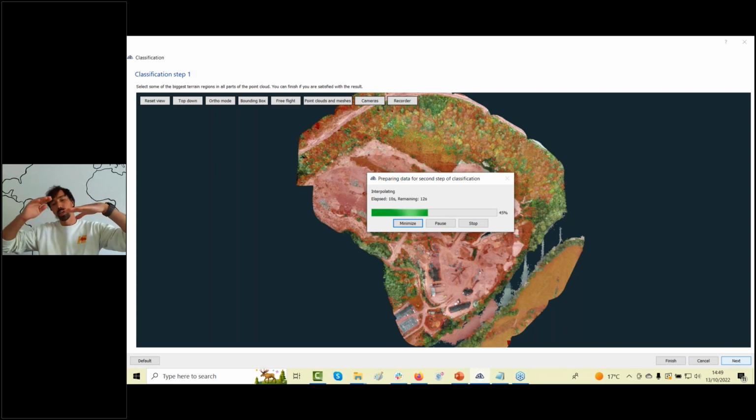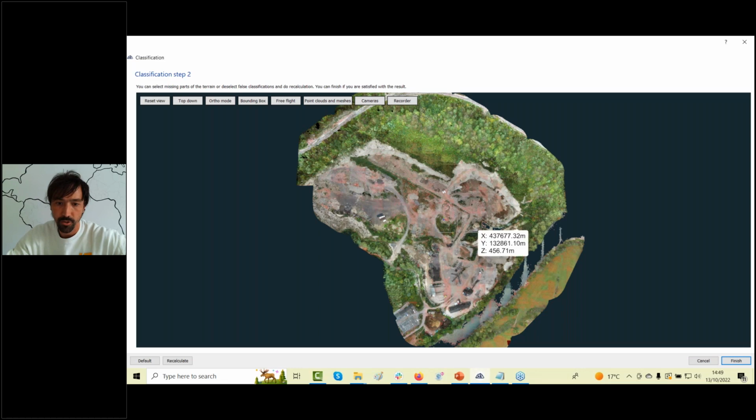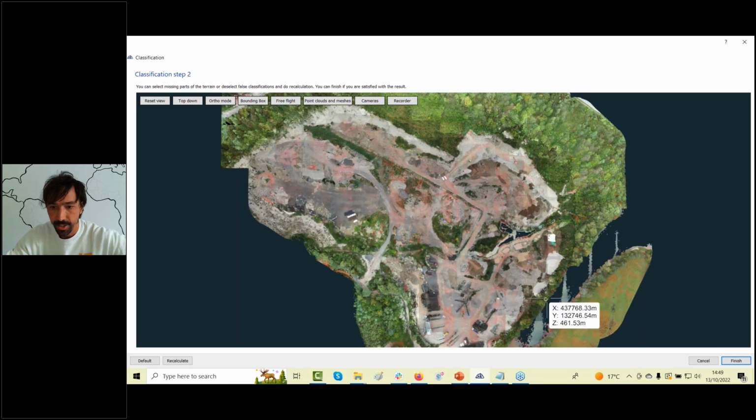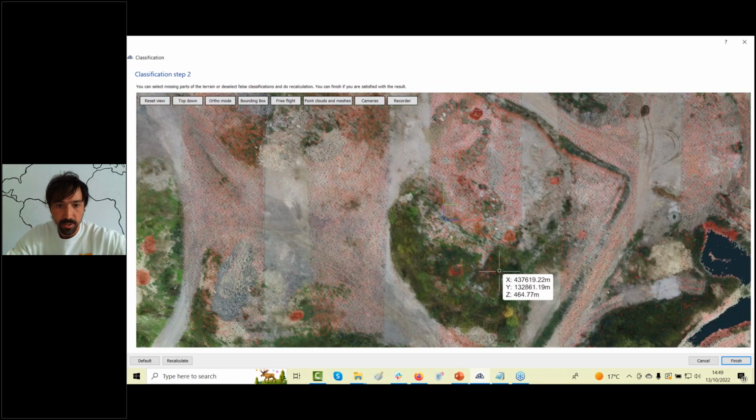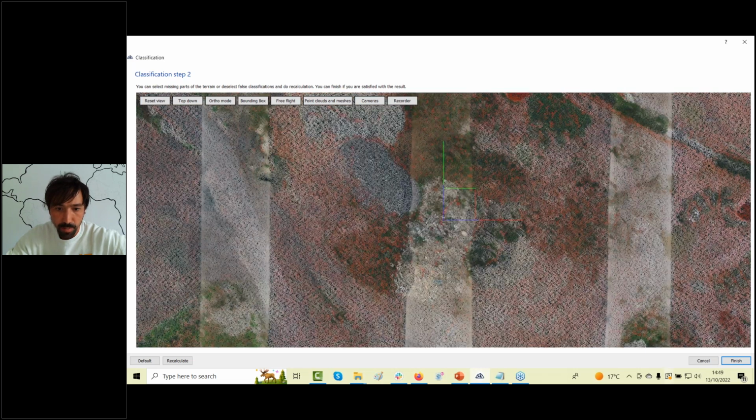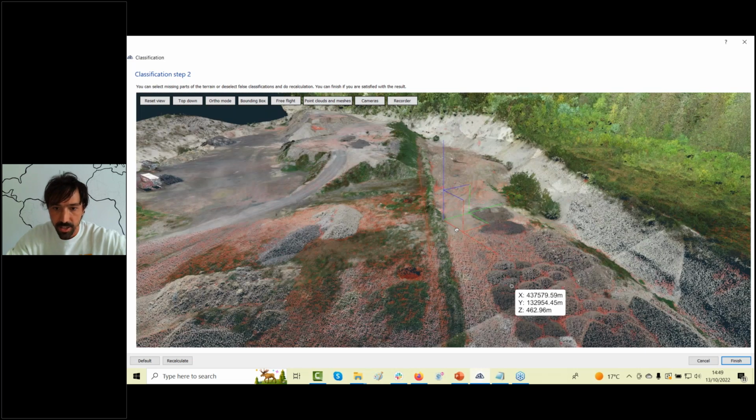Now we are looking at which points are on the upper side and which are on the lower side, what the actual step between points is, the angle between them, and all those parameters. Based on all those geometric parameters, we're trying to find the terrain points, and the result is here. As you can see, all colored points are detected as terrain points.